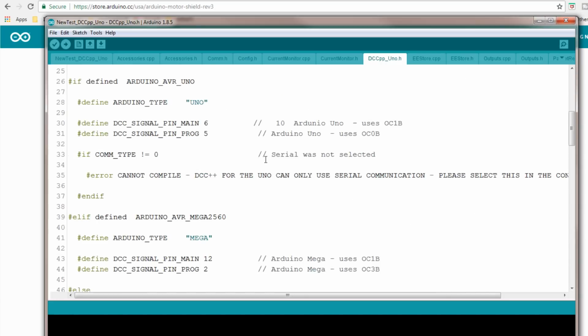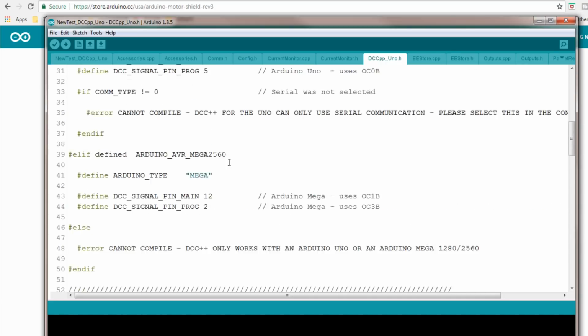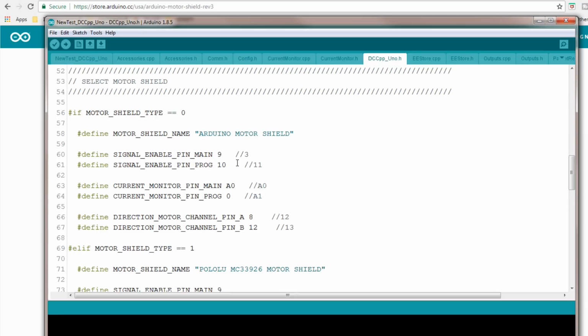Now, there's more timers in there, like I used 6, but it didn't quite work. I got this thing to work one time, but it didn't work fully. I was able to change settings in JMRI. I was able to write to it, but I wasn't able to read back. Now, when I went to the CV page, I tried to write the entire page, and it skipped every other one, so there's some kind of a timing issue in there.